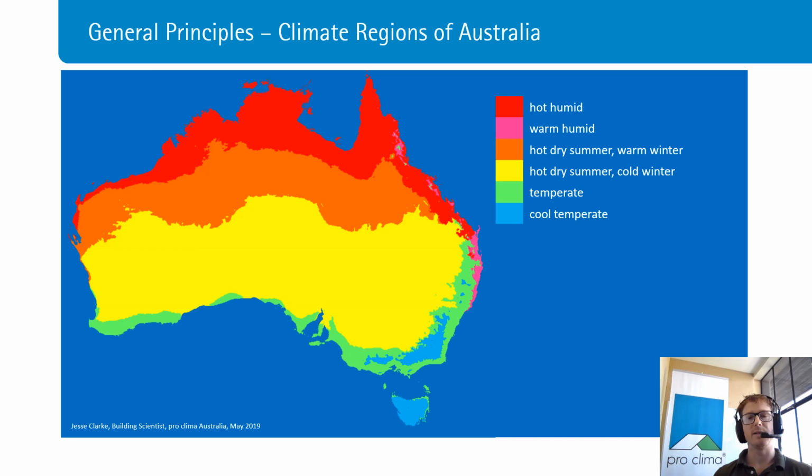The other thing we need to consider when designing weather resistive barrier systems and weatherproofing systems is the climate conditions in which you're designing your building. So in cooler climates where buildings are normally heated, so in cool temperate regions, you've got warm humid air on the inside of the building, and this can actually push water vapor into the structure. In the tropics, when you've got lots of water vapor in the air outside the building, the air conditioning can suck water vapor back into the building structure.